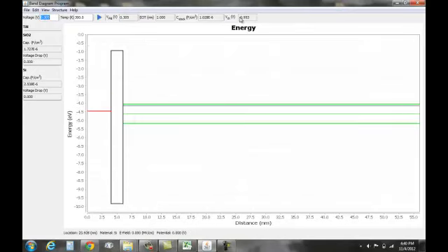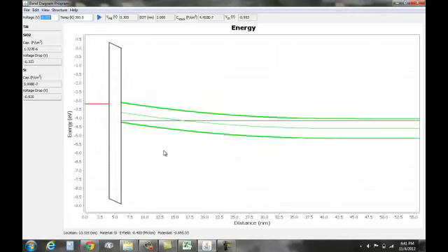If I want to put in the threshold voltage, I can see where the Fermi energy is at the interface of the silicon dioxide and silicon. There it is, showing that that's where the device essentially turns on. When that amount of voltage is applied, the Fermi energy reaches this point in which the majority carriers are now holes. So these are the specific functions of this program. Now, let's say that I want to edit a particular material.